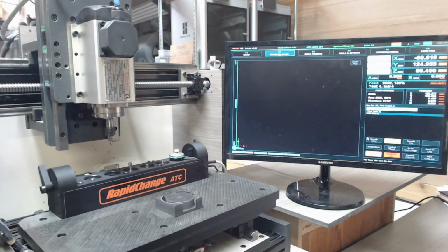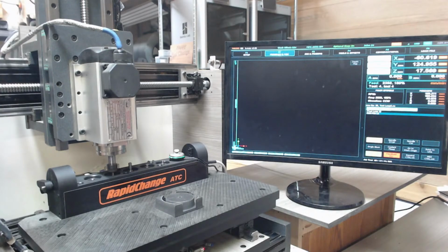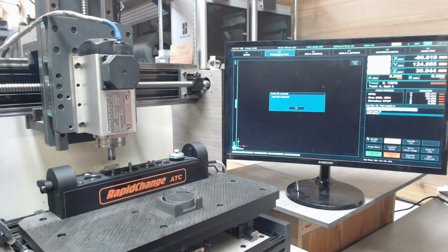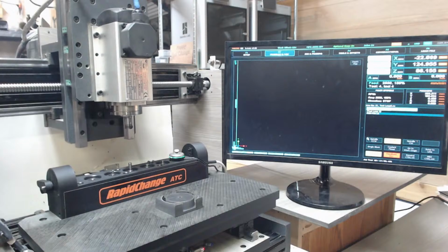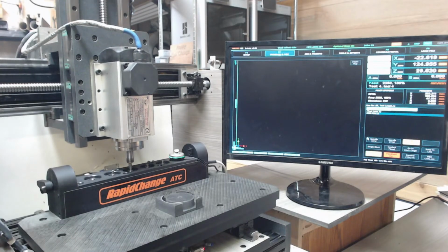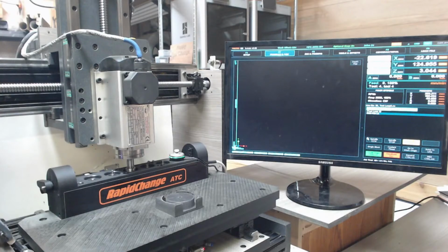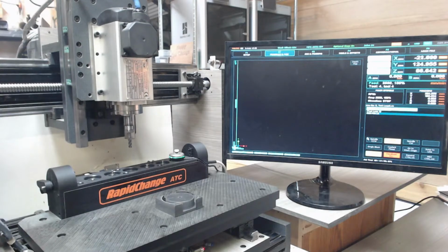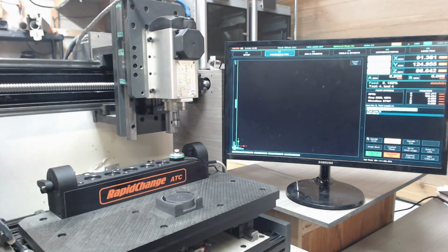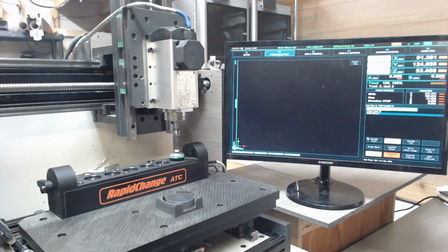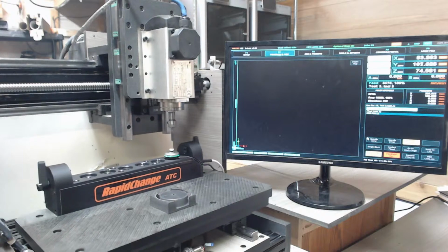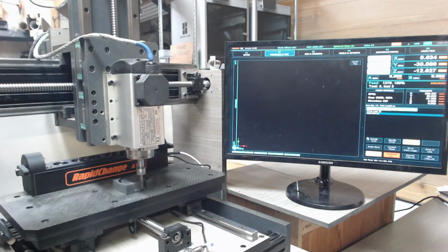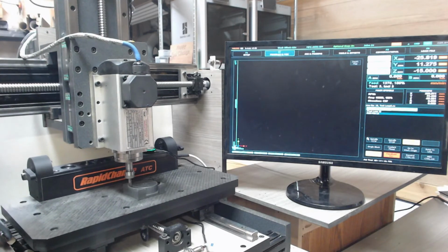I think I've got it at the high end at like 2,500 millimeters per minute, which isn't super fast, but rack and pinion is where it's at for speed, I think. I've got a machine half built, a 4x4 or 1,500 by 1,500 millimeters, that I can't seem to find the time to put together, but I've got helical rack and pinion for the Y and X on that, and kind of dying to get it put together because that's what I'm going to use to build these kit machines if I ever get around to them. I think it'd be cool to get a small desktop machine, maybe a little bigger than this one, on the market with the RapidChange built in and everything all configured and ready to go.